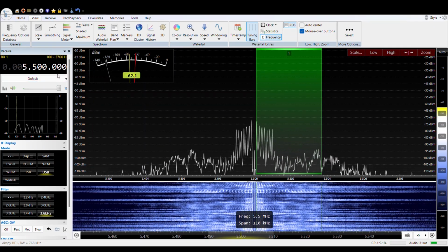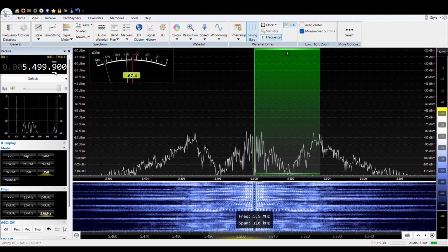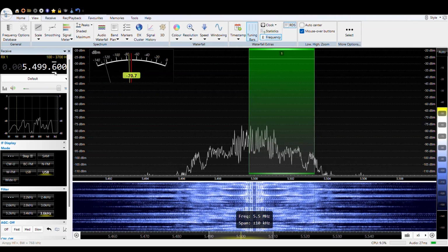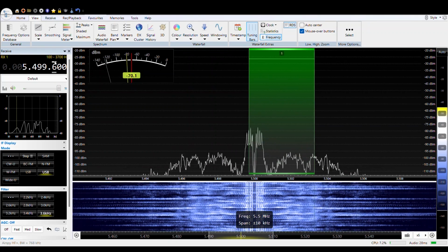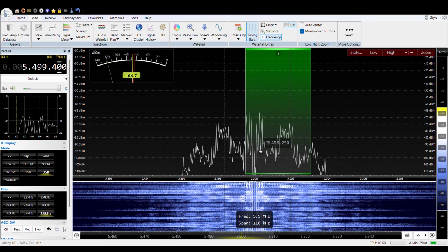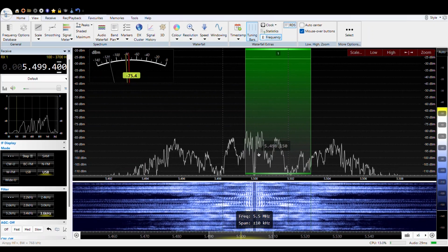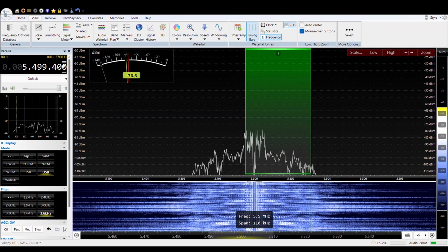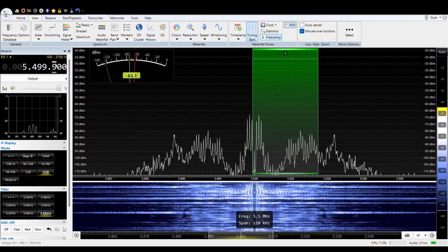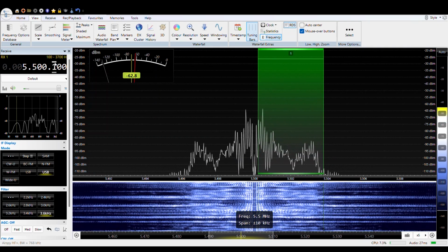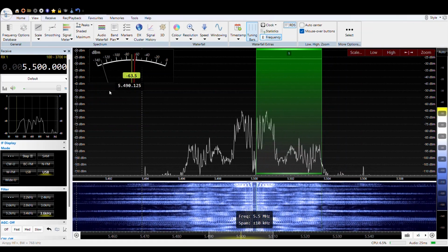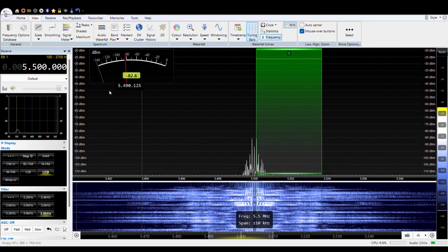And just one last little thing to play with here, of course, just like anybody that's familiar with communicating in sideband, if you start getting off frequency, the voice starts to get really distorted, and you get either some carrier bleed through or just some 60 hertz hum that's being picked up that we're hearing in the signal there. But yeah, if you're right on frequency, you're going to sound good. If you're a little bit off, you're going to get some pitch shift there. So all in all, I'm pleased with how this is working.